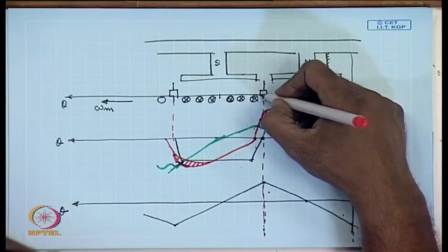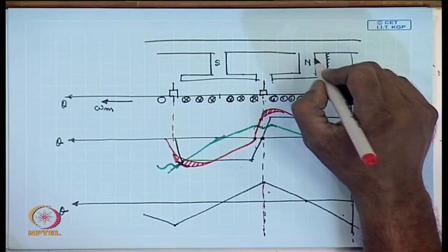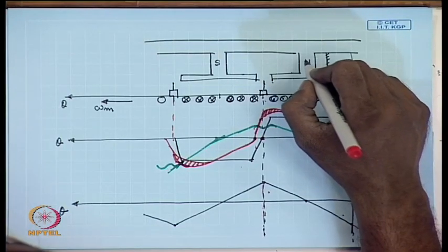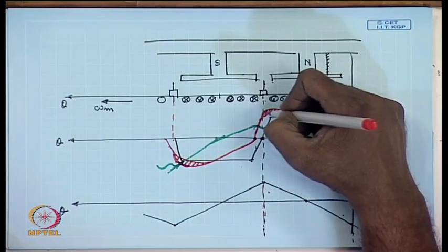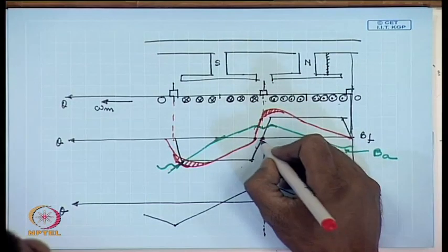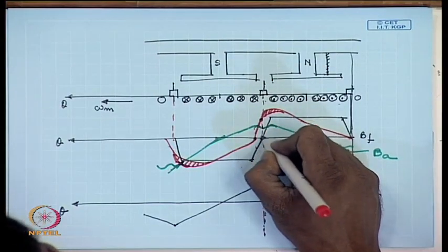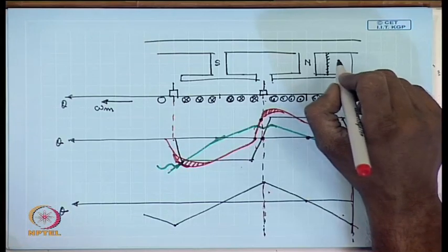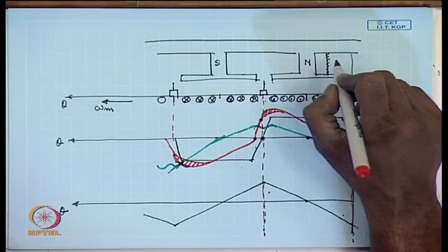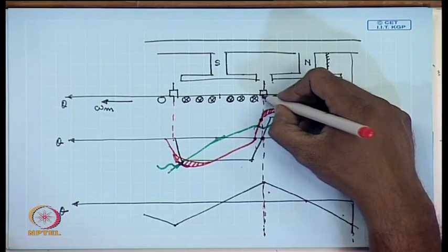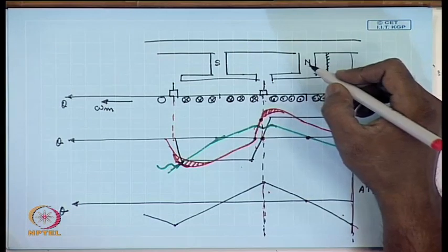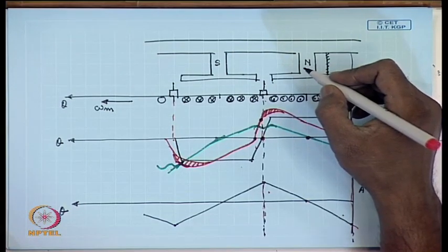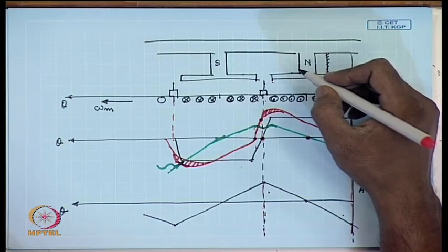The brushes are usually placed at the zero crossing of the field flux, but because of armature reaction, the resultant flux density at the position of the brushes is no longer 0. Hence, the coil that will be connected to the brushes will not have a 0 induced voltage at the moment of commutation.